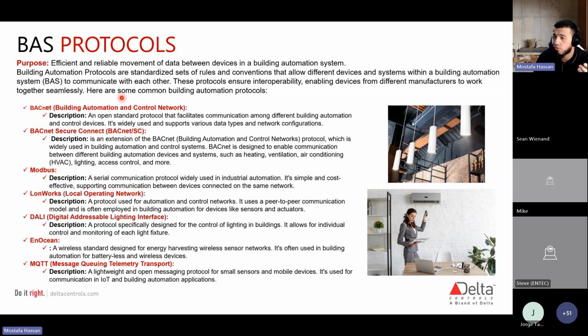This is an ASHRAE standard, ASHRAE 135. It is not a proprietary creation. This is something open to all manufacturers. This is the most common one used in the building automation industry. And you should definitely be specifying BACnet, if not BACnet Secure Connect, which we'll get to in a moment. BACnet Secure Connect is actually an encrypted form of BACnet. The ASHRAE committee decided, hey, why don't we not reinvent the wheel to encrypt data? Let's just use how the internet works.